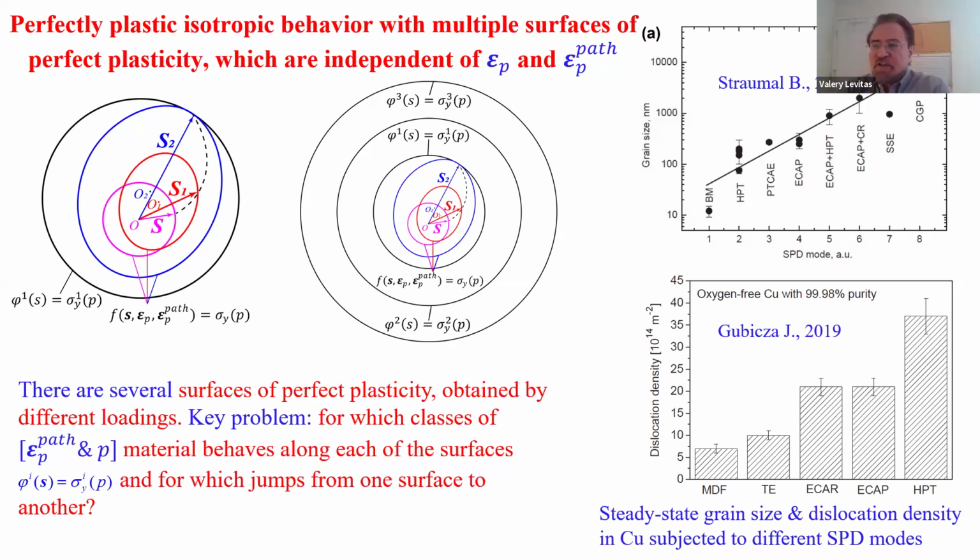Generally, yes, because we are working at room temperature. There is a large community which produces high pressure torsion for a living, mostly without in situ experiments, to produce nanograin materials, high dislocation density materials, and these materials at room temperature can stay for several years without changing grain size. So maybe there are some exceptions. I am sure that what you said will happen at high temperature, because then we have dynamic recrystallization.